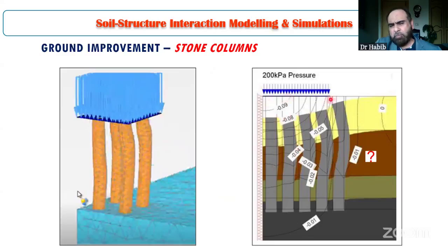It is also based on how the foundation is acting, whether it's a rigid foundation or a flexible foundation. This information we can get, and in the same 3D model we can see it as well. Then for the behavior of the peripheral columns, whether we have to provide one periphery column or maybe more, it also depends on the results of the simulation.